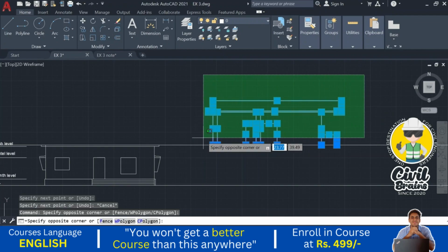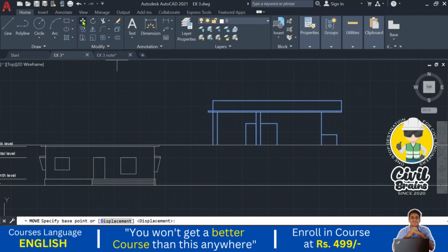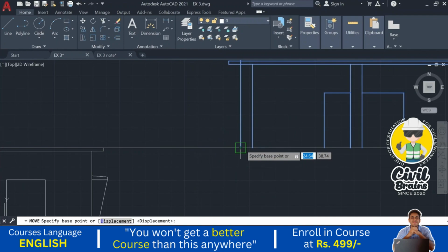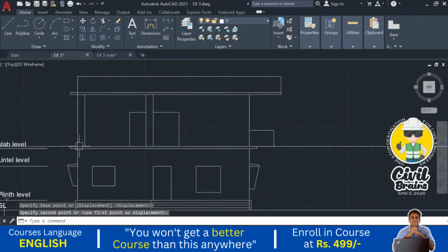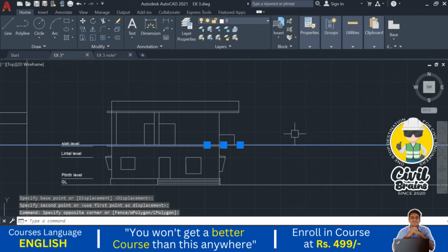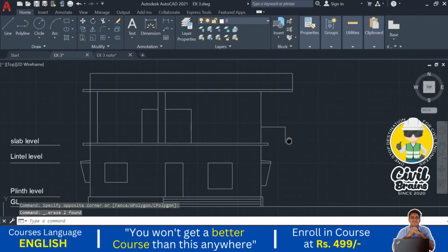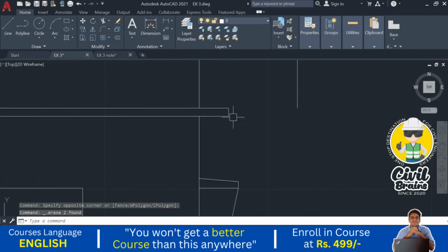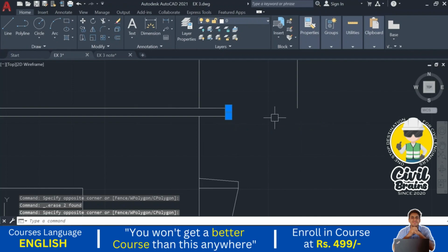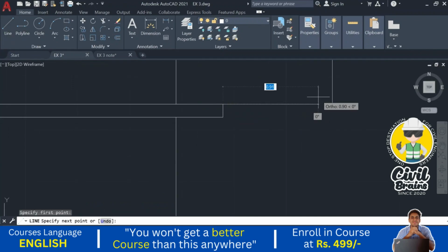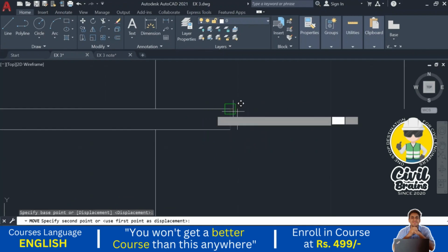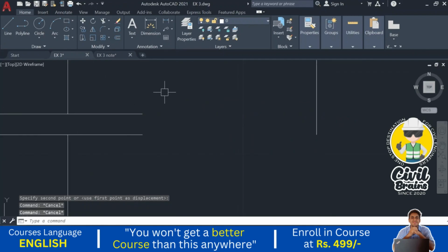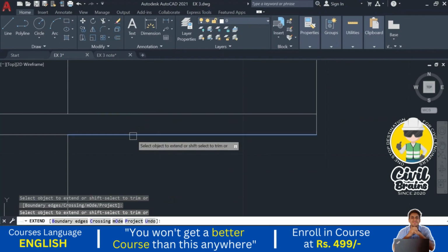select this one, go to the move command, click on move. I click on the reference point and move it above the wall, and this slab level I just delete. Oh, okay, so here also we need to move this slab. Move, and extend, EX, enter.